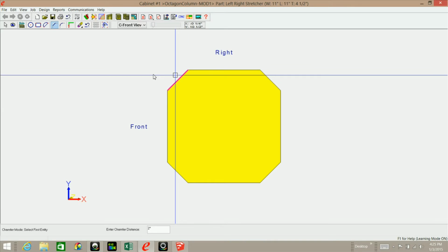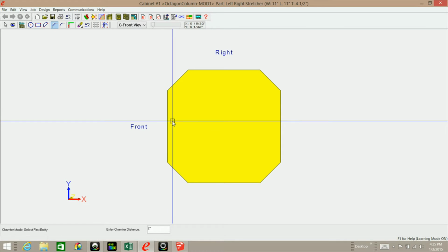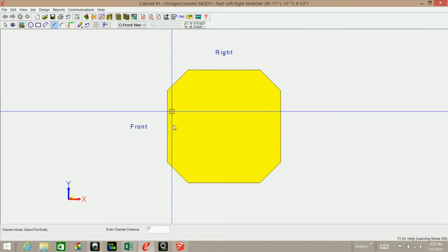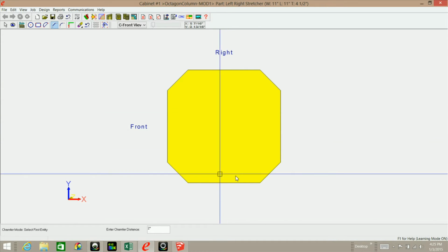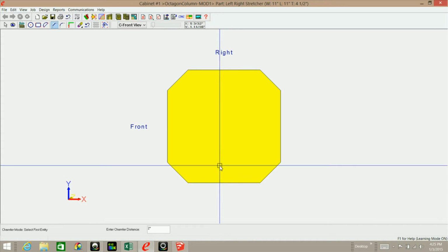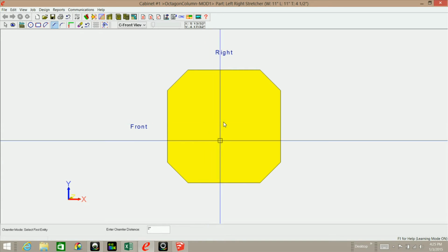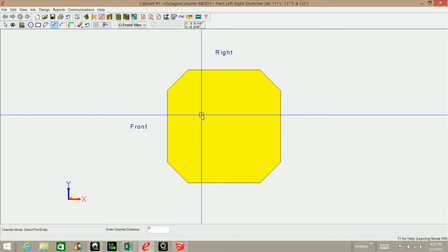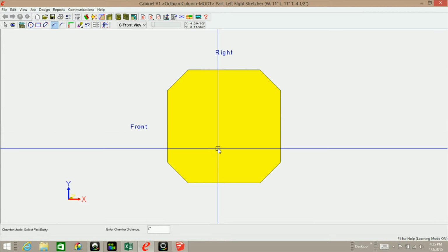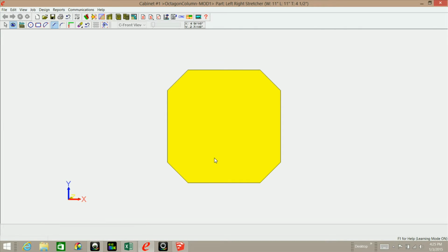What I want to do now is show you how you can make this more authentic by offsetting these by the material thickness that you're going to use for your base molding, and make a pocket so that if for whatever reason you need to or want to put a door on this, or leave one side open and actually access the inside of this column, this particular part will not be protruding 4.5 inches up inside your cabinet. If I click on the eyeball here, you'll see what I'm talking about.